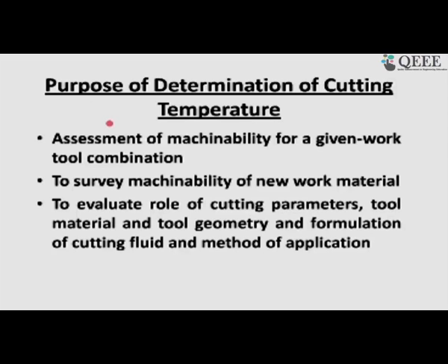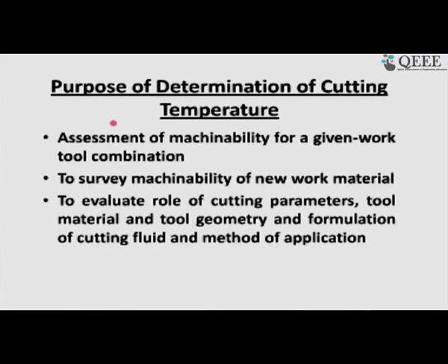So, when it is a cutting fluid, we pay attention to both these things. One is the tribological property, reducing the friction. Another is to bring down the temperature by cooling. So, both the things are there, and one can judge this capability of the cutting fluid, and net effect should be reduction of temperature. That is the final result. So, we go to the next one.